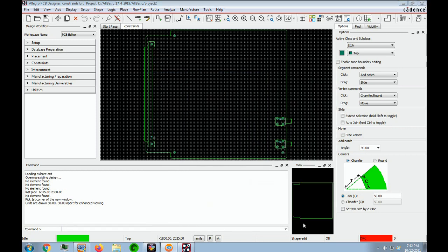In this section of the lab, you will first turn on the layers that display the room information. You add 4 rectangular rooms and give them each a name. Each set of coordinate points that you enter becomes a diagonal corner of the rectangle.